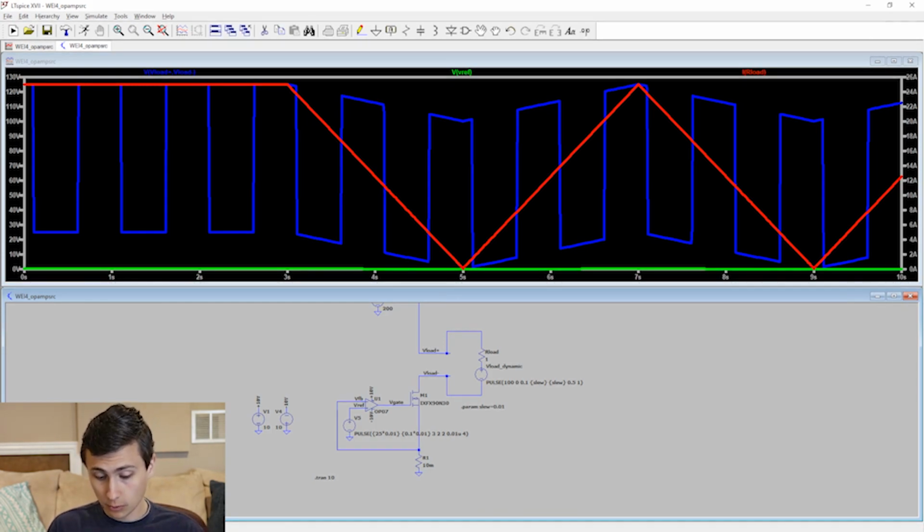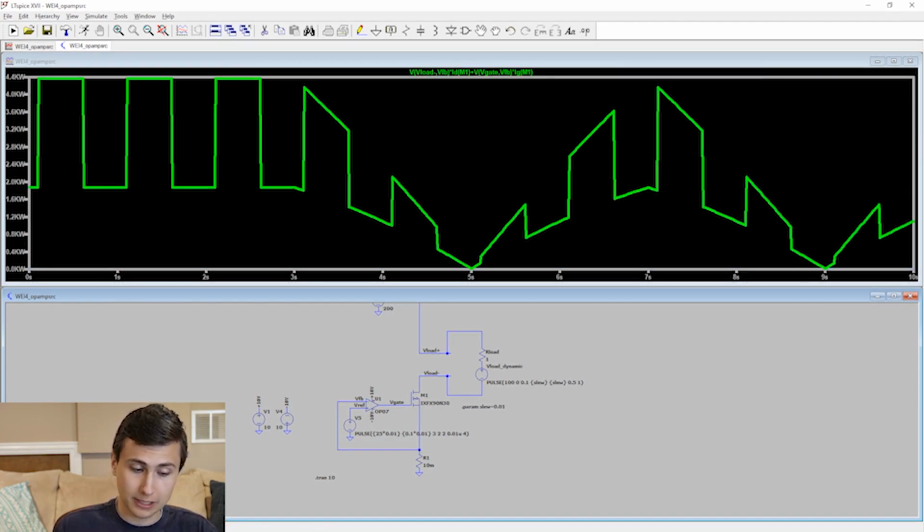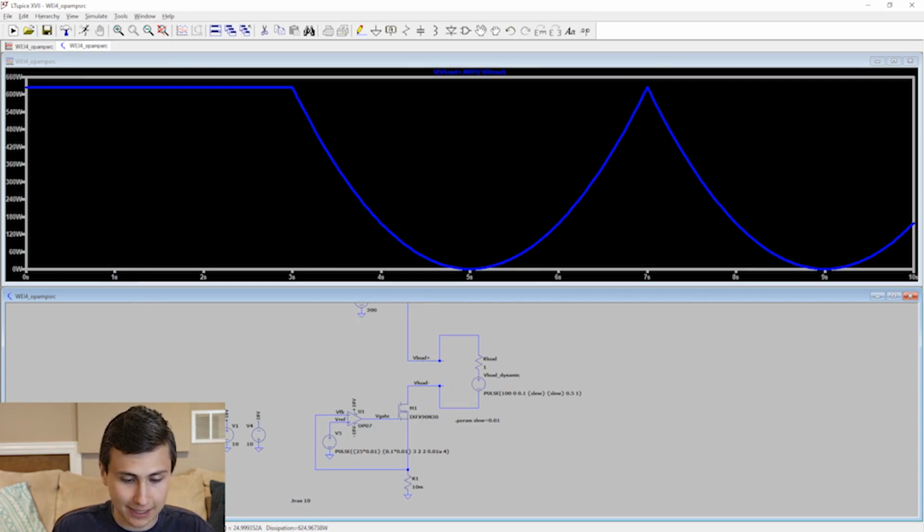We have it configured this way, though it certainly is not ideal. We can see that we dissipate about 6 watts in that current shunt. When we're regulating, we're dissipating anywhere between 2 kilowatts and 4 kilowatts in this MOSFET. Yikes, to maintain a relatively constant load across that resistor.